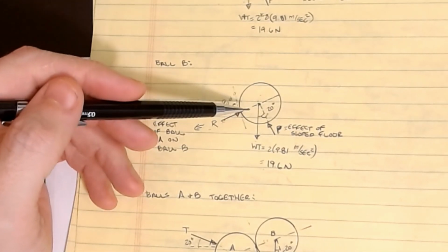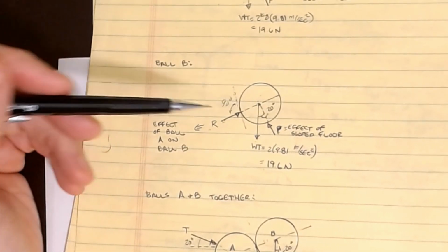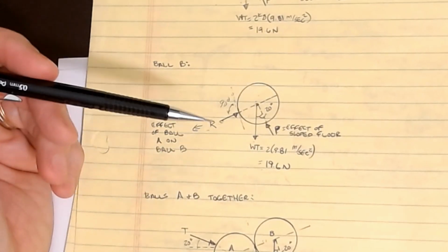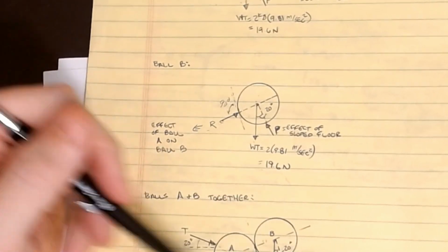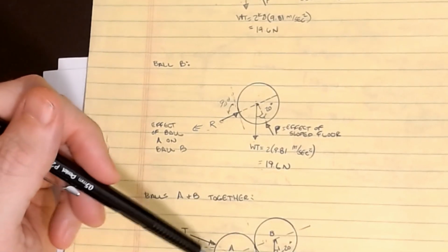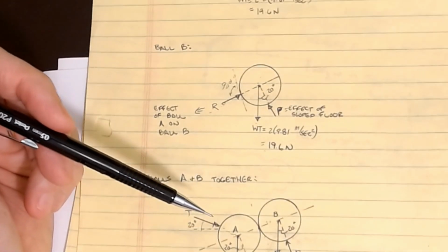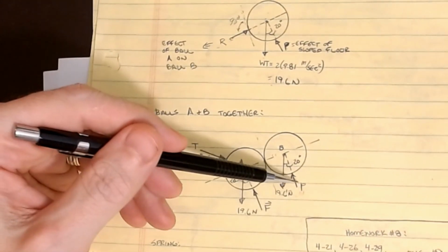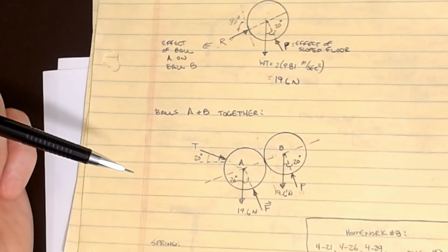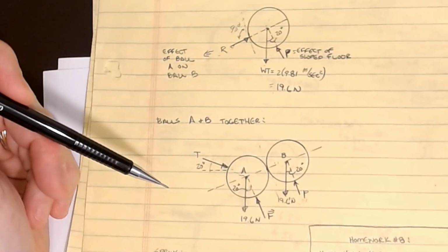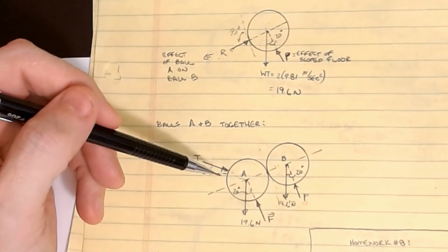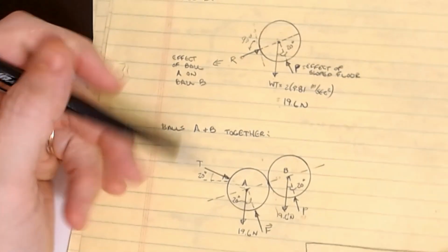And then I'm going to have that free body diagram, and the next step is always write equations for it. And that's what we're going to look at doing. Eventually, in a lot of cases, if it's statically determinate, you can work your way through and actually find all of the unknowns that you couldn't have solved for back on the original. That's the problem with this one, I have 1, 2, 3 unknowns, okay? But I would only really have 2 equations to work with on this. And so that's kind of the nature of what we're looking to do. So I hope that's made some sense to you.